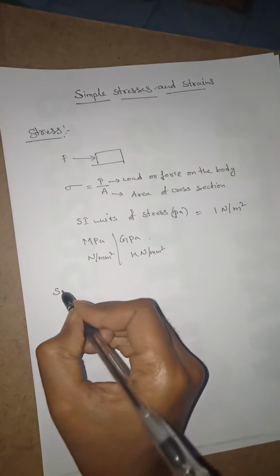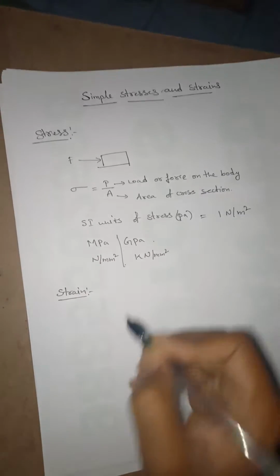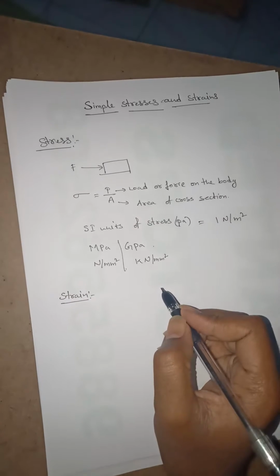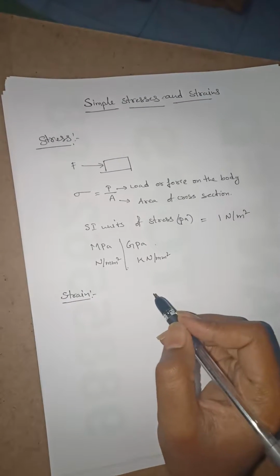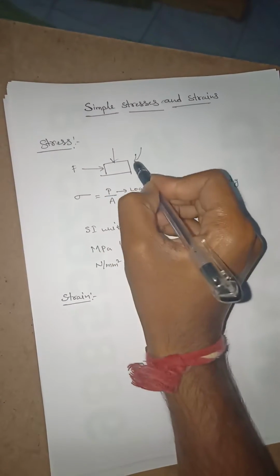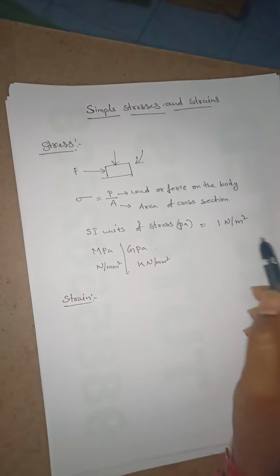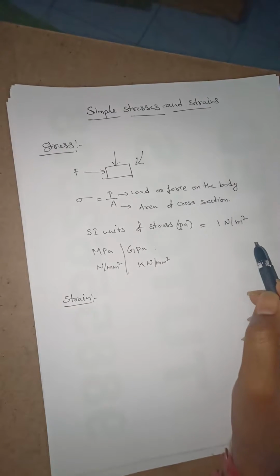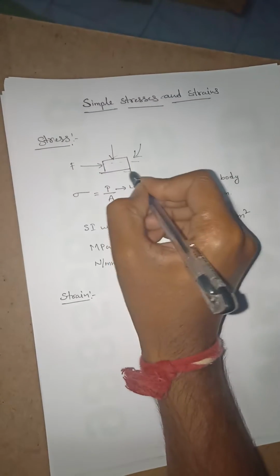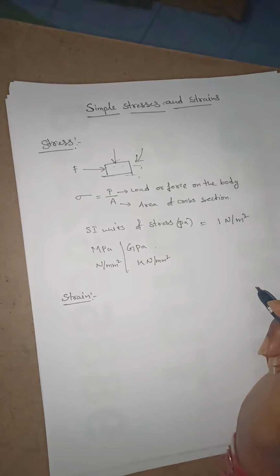Okay, now let me discuss strain. What is strain? As already mentioned, whenever a single force or a system of forces acts on the body, it undergoes some deformation, and the deformation per unit length is known as strain.